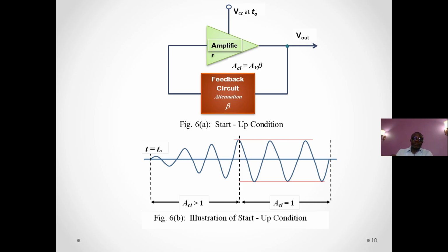The amplitude becomes higher than the previous one, and it continues until it gets to the point which we marked, probably T2, the next dotted line down, which is the desired amplitude you want to maintain. At this point, this system must be self-correcting by retaining the gain at 1.